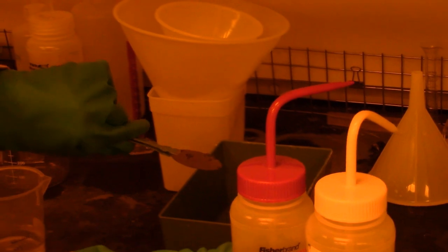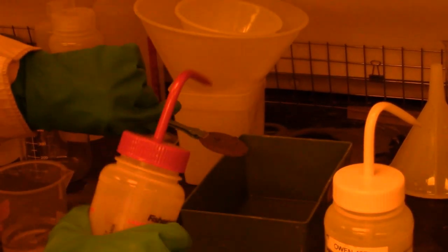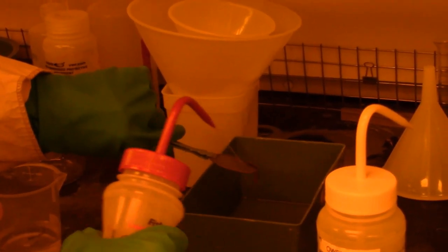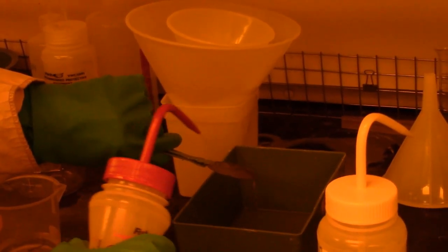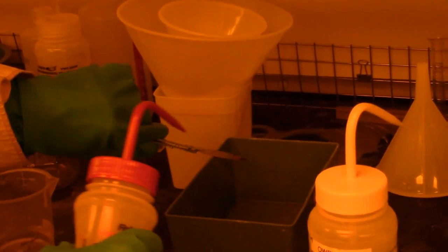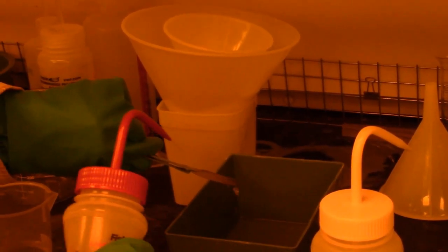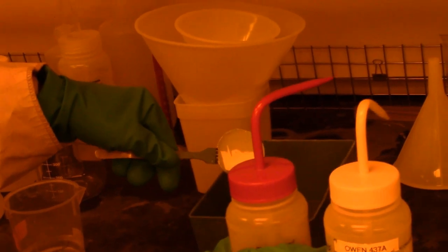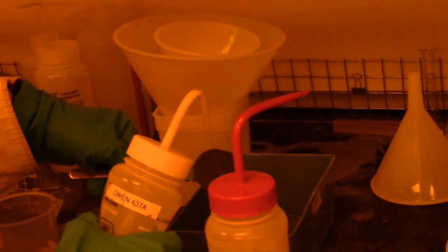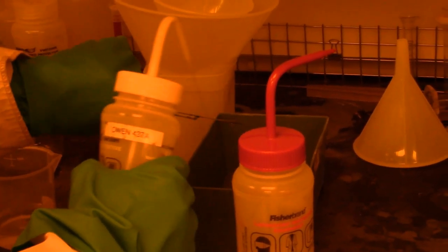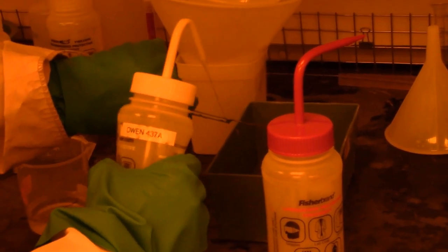Remove the photoresist on the front side of the wafer using acetone. Then make sure that this is thorough, so there is no residue. Remove any residues from the acetone clean using IPA.